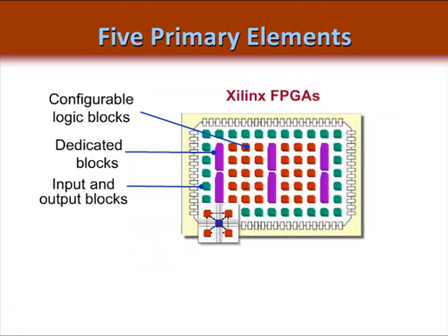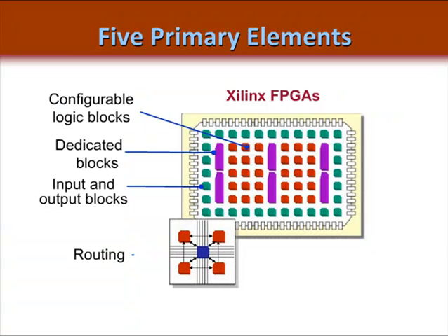Outside of the CLBs are large arrays of routing resources. The routing is connected together with switch matrices. The switch matrix allows many different lengths of interconnect to connect a signal from any source in the FPGA to any destination. This structure is designed to assure routing flexibility so that all designs can route to completion. It is also designed to assure short routing delays so that system performance objectives can be obtained.